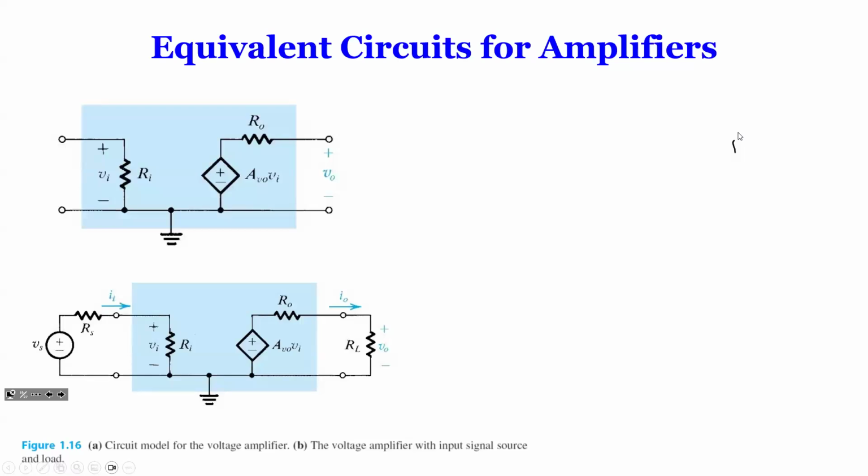So pretty much everything is here, right? Because that 1 ohm versus this 1,000, this is only 0.1% of the input. So primarily it's all here, so we can neglect it. But if we flip around, say this internal impedance is 1 kilo ohm, but the input resistance of this amplifier is 1 ohm, what happens?